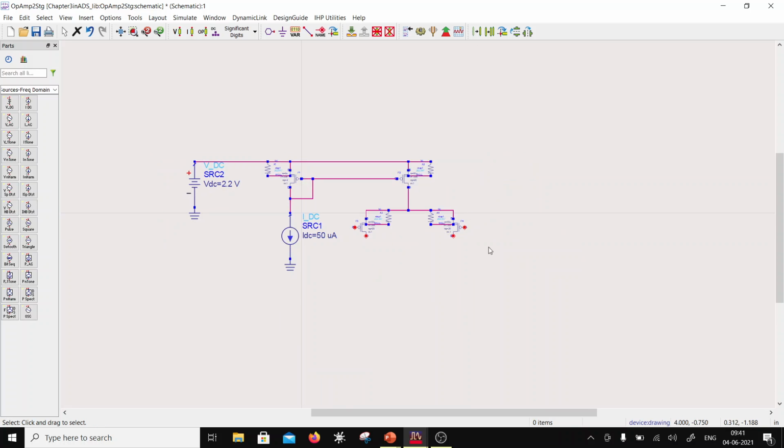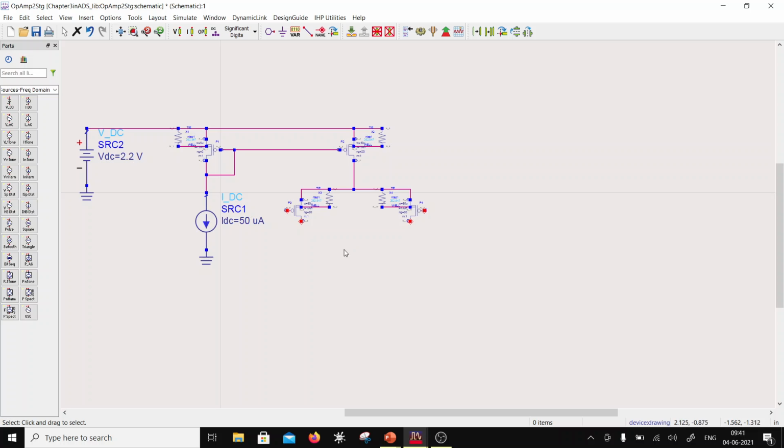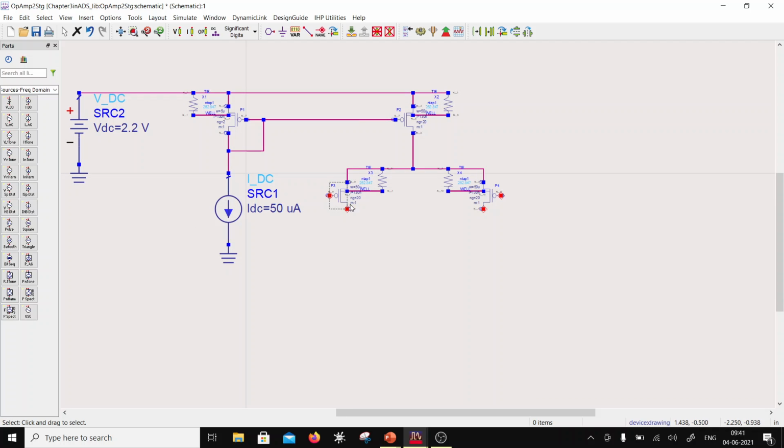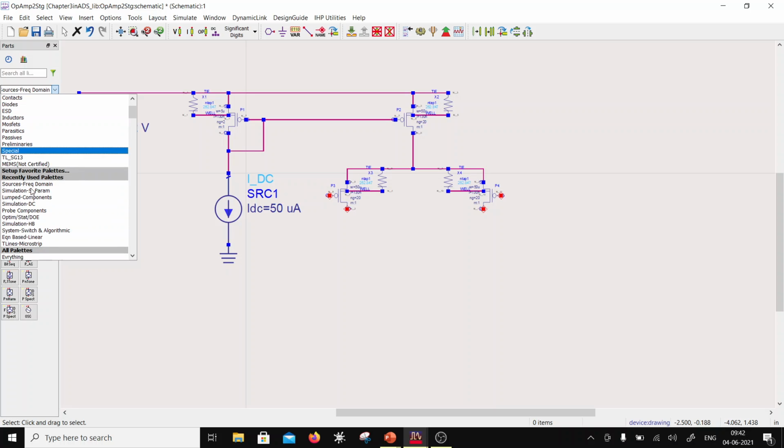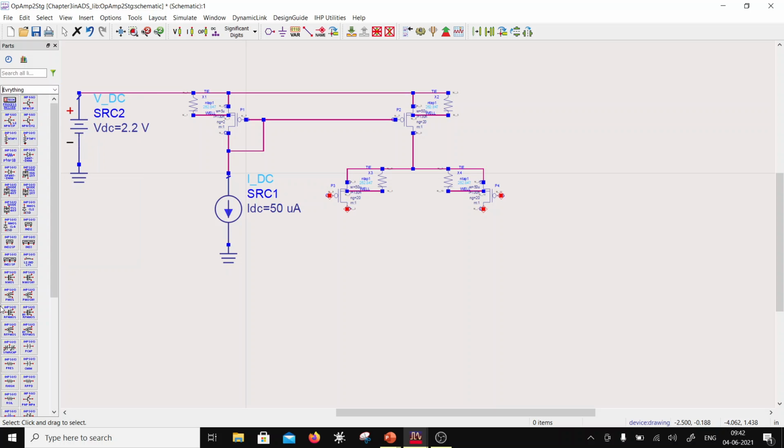Okay, so this is going to be my gain stage, a differential gain stage, and then I need a load, right? So this is 20, so I would do half of that. So basically I'll use 25 and 10 fingers. So I'm going to choose an NMOS device here. That's an NMOS device, and this NMOS device is going to be 25 into 10.